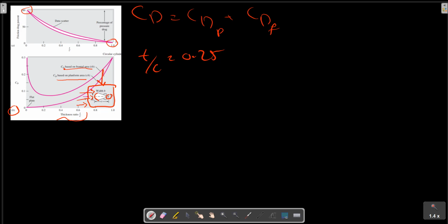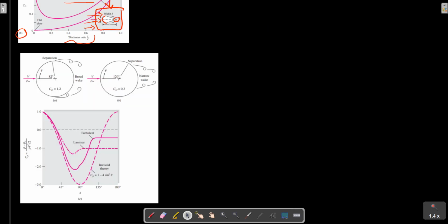There is also another example shown in this picture. This picture illustrates the dramatic effect of separated flow on the subsequent failure of boundary layer theory. The theoretical inviscid pressure distribution on a circular cylinder will be discussed in chapter 8. It's shown as the dashed line in this picture.